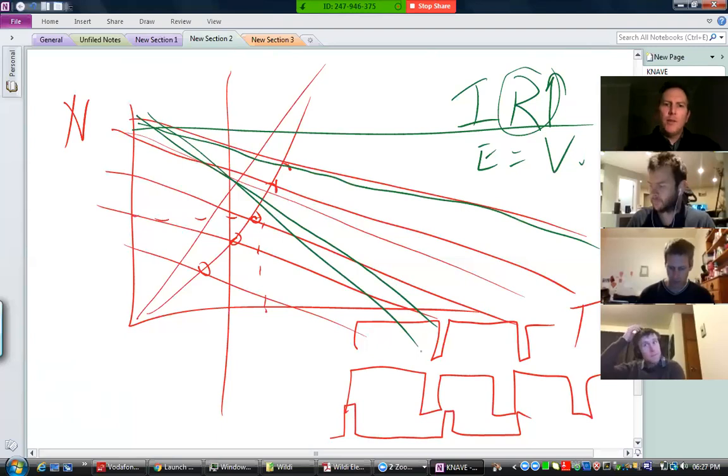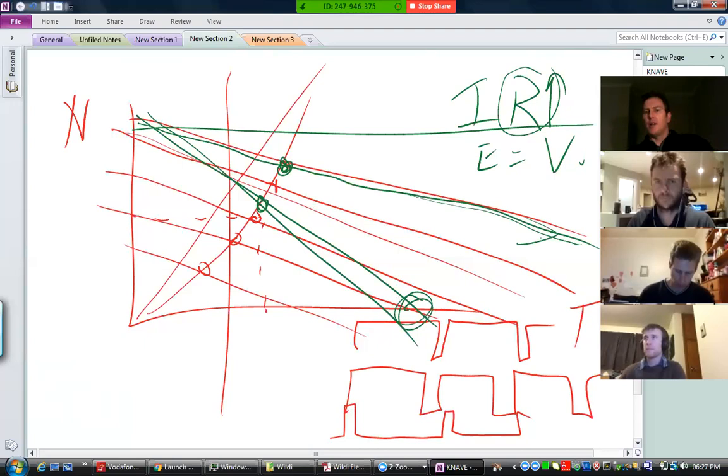Again, that would mean instead of intersecting perhaps over here in one case, we intersect now over there in some other case, and it would get some speed reduction. But it's never going to be as good as getting the whole voltage curve shifting down. For example, under those conditions, your maximum torque would be out here somewhere, whereas normally the maximum torque we could go right to the outside of the screen, where it would intersect the line. So there are certain limitations for those methods.